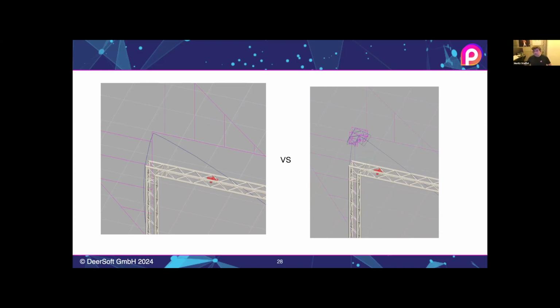The main advantage of doing this is that it's way more efficient to calculate one element for this truss than to calculate 500. If you used more elements to represent this beam, you would just bump up how many calculations you need to do.